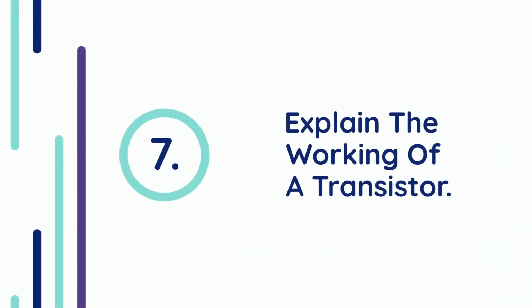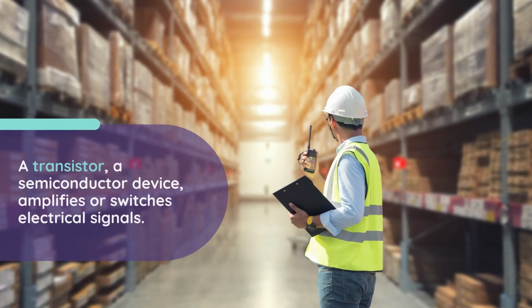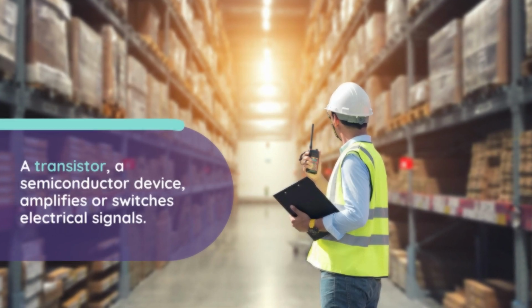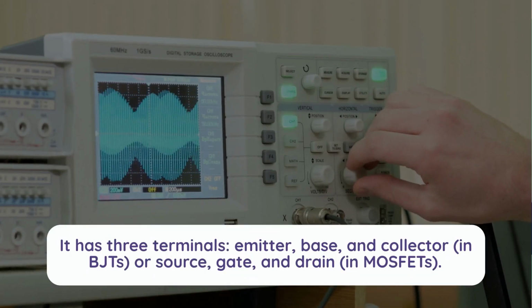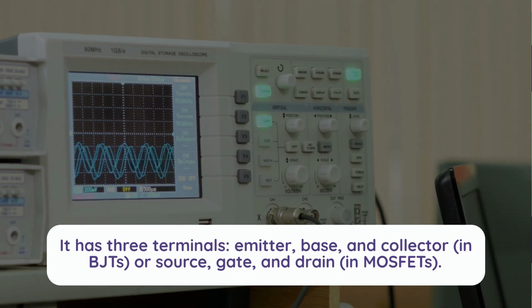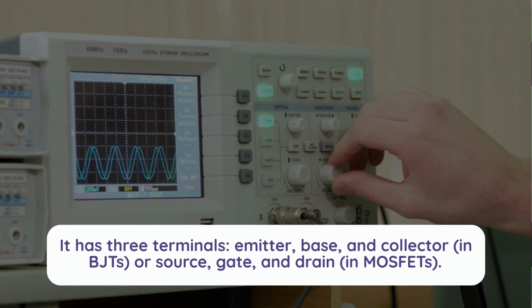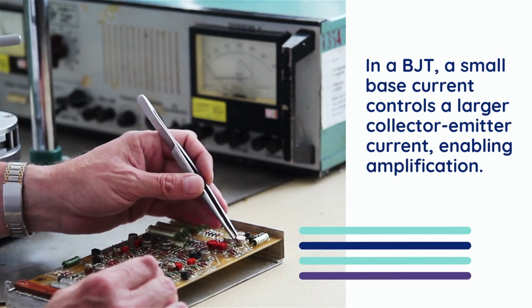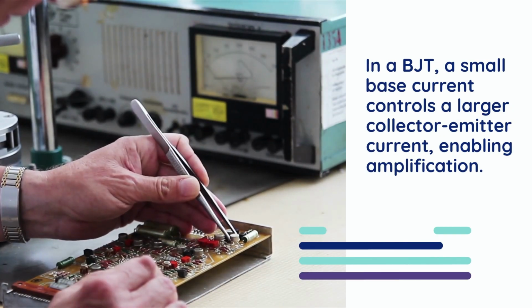7. Explain the working of a transistor. A transistor, a semiconductor device, amplifies or switches electrical signals. It has three terminals: emitter, base, and collector, in BJTs, or source, gate, and drain, in MOSFETs. In a BJT, a small base current controls a larger collector-emitter current, enabling amplification.